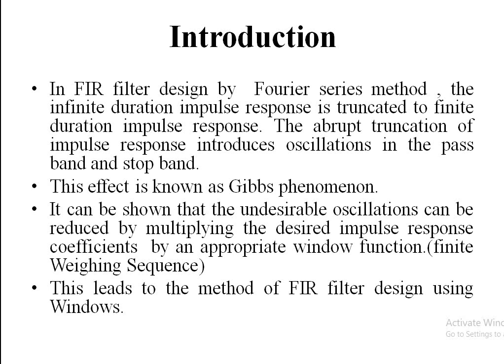To reduce these oscillations, which are undesired in nature, generally the Fourier coefficients of the filter are modified by multiplying the desired impulse response coefficients with a finite weighing sequence, which we call a windowing function. This leads to the method of FIR filter design using windows.